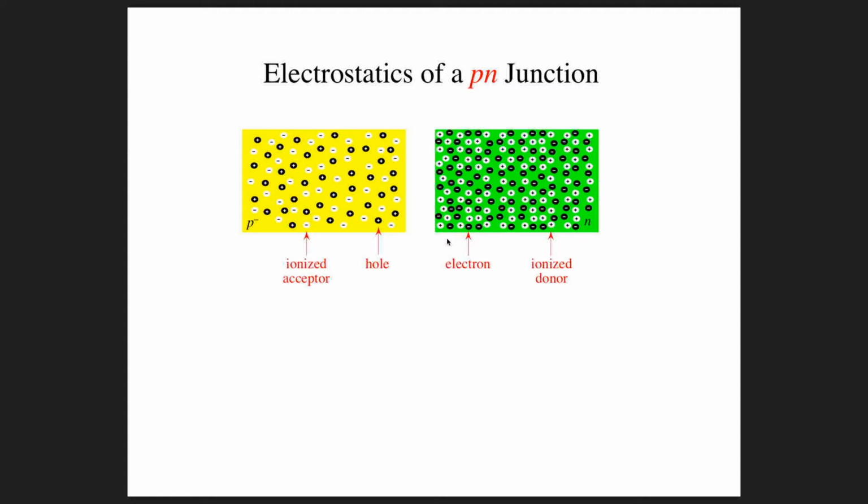And then if we have a really heavily doped area, we denote that with a superscript plus, so it would be like a P plus or an N plus region. And that might be kind of in the range of 10 to the 19th per cubic centimeter to 10 to the 21st per cubic centimeter, maybe 10 to the 18th, 10 to the 20th per cubic centimeter, something in that range. And when you're getting into that sort of heavily doped area, you're not quite to the level of a metal, but you're pretty close. That's a pretty conductive chunk of silicon. And then we sometimes will dope even at a slightly higher level, and that would be called degenerately doped. And that is practically behaving like a metal for all intents and purposes.